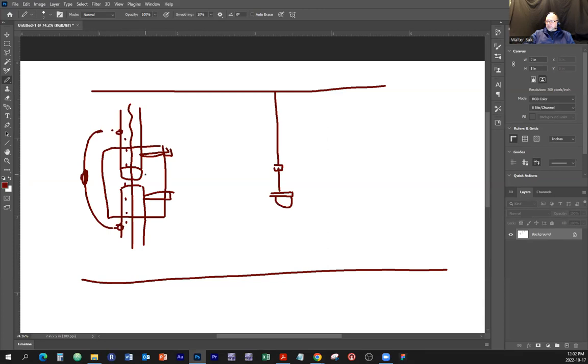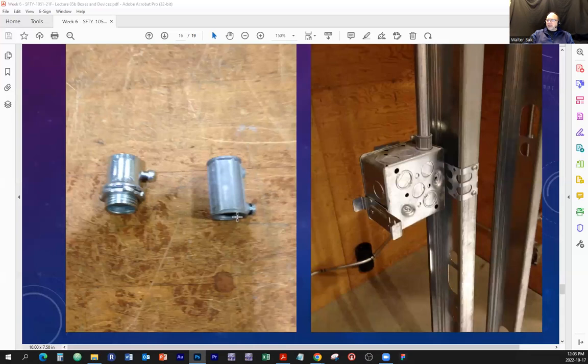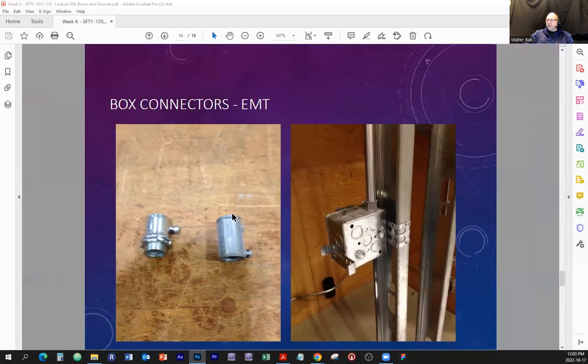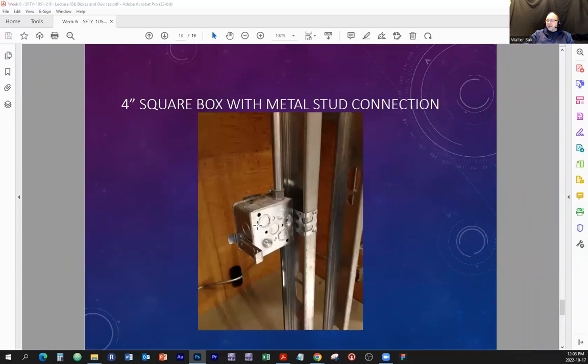Or sometimes what people do is they drill a hole and put in a screw right there, through the metallic tubing and over here as well. They drill and they basically put a screw right in. So it's being held as one piece. Do not use that coupler as something that can hold weight. Everything should be mounted or fastened to the wall or to this timber stud.